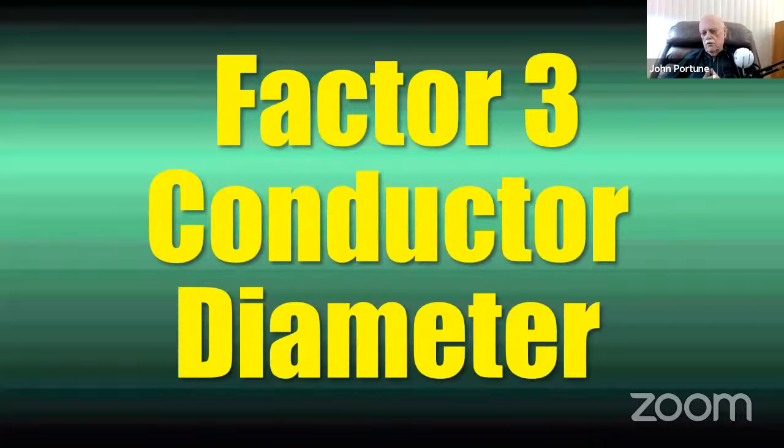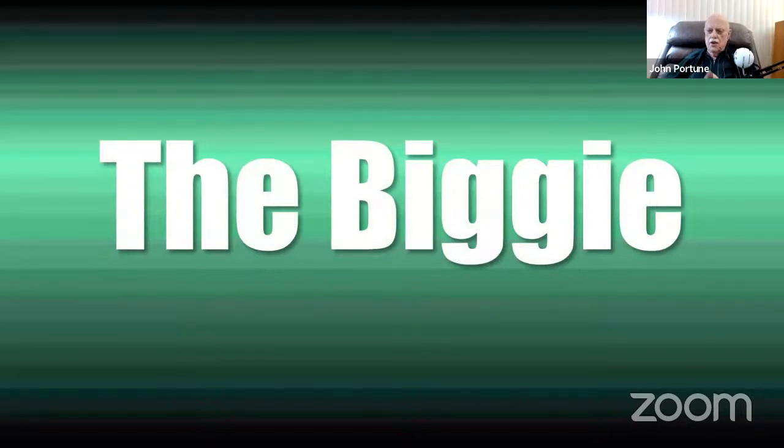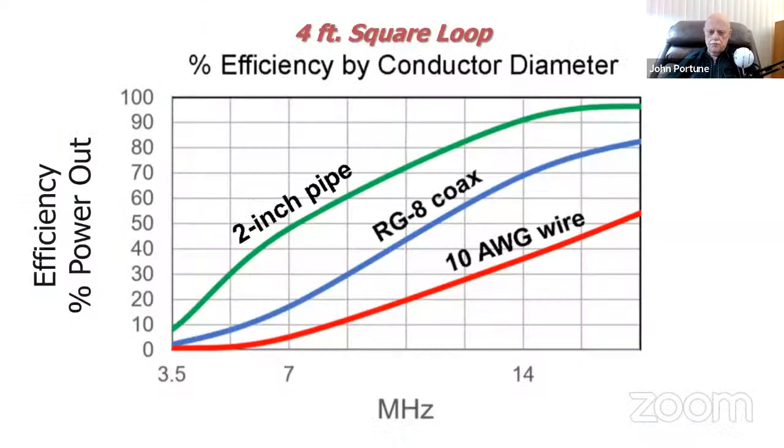All right. Factor 3, conductor diameter. This is the biggie. This is the one that all mag loops must pay attention to unless they want a very unoptimized loop. That's why most of the loops you see on the internet, most of the designs that other builders use, are only built by guess and by golly, and they don't take this into account properly. In fact, even some of the commercial manufacturers don't take it into account correctly. Let me demonstrate this to you.